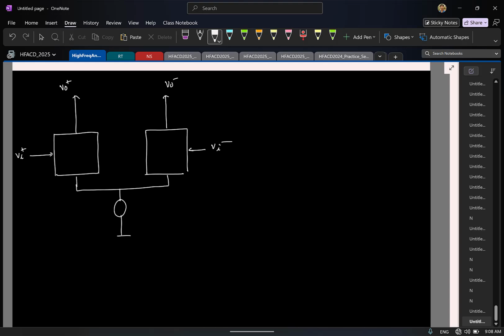Of course you need to have common mode feedback for this structure. And again I'll draw it at a block level. Let us say you sense the common mode using something, and then you have something that goes and sets the common mode. It's a very block level representation. And if you look at the CMFBs that I have drawn in blue, you can notice that this part of the CMFB is common to both half circuits, whereas the common mode detecting part is individual, right?